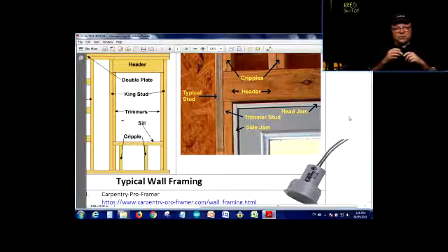The best time for running a wire in any kind of building or facility is before the drywall goes on, because you have the freedom of running the wire, and after the air duct or HVAC people leave. The crews that install the air ducts have a certain job to do and they're going to do it fast.